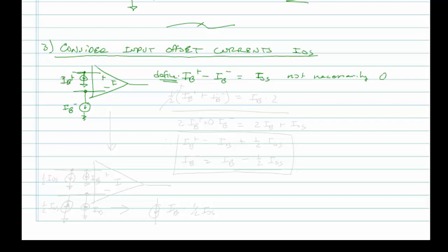Photolithography is used to produce the little transistors on the silicon die, and there are some accuracies in the feature size, right? So any variations could result in the bias currents not being exactly the same.